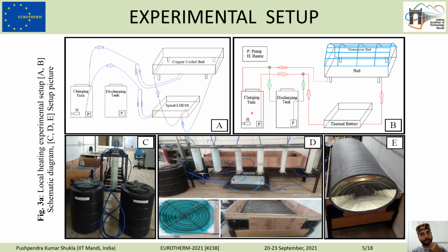During off hours we used this heater for heating the water, and we took 100-liter tanks. Why did we take 100-liter tanks? Because it reduces any kind of fluctuation in the first few cycles. For the first few cycles, the temperature decays rapidly, so for that only we took a large volume of water, so that these fluctuations can be avoided.